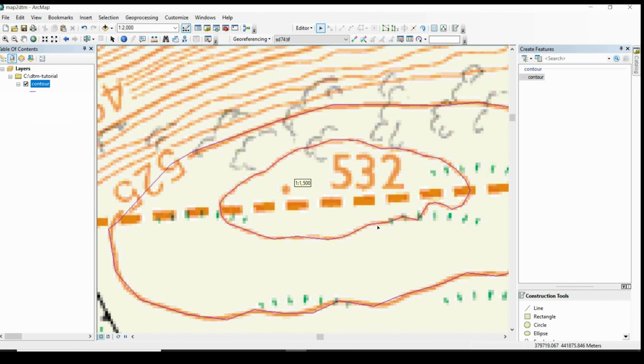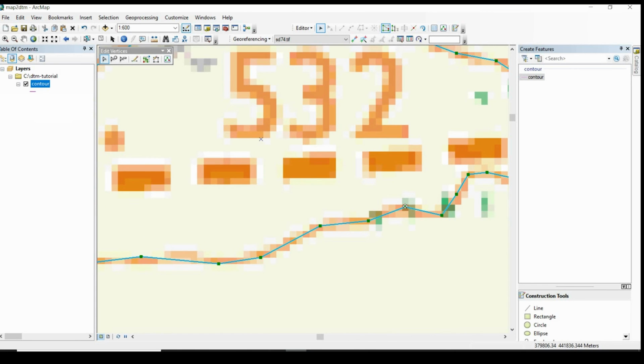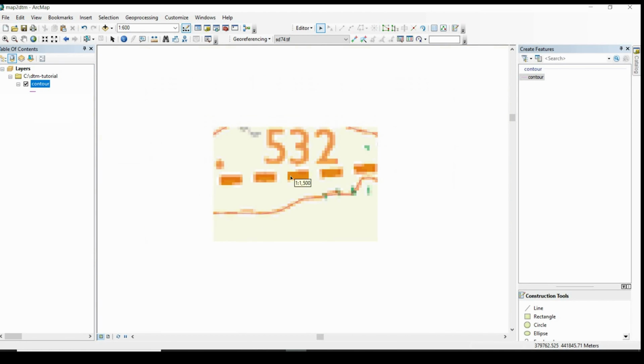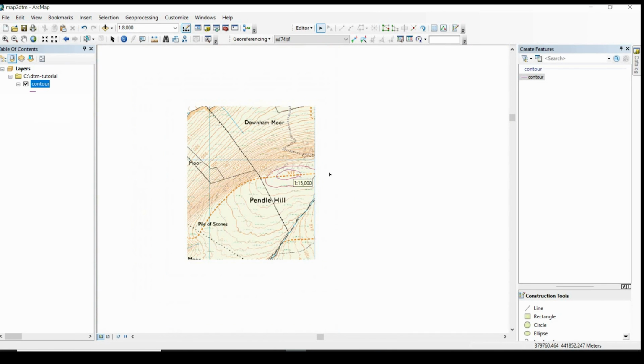Now to edit this contour line, guys, as I mentioned here, you would go here to pick this tool, the edit tool, and then double click on the contour line. And then you will have all of these nodes. You can just shift one down here or up and then adjust them as you would like. Okay, and then once you've done, double click, you have your contour line. And you will do this for all of the contour lines in your map.